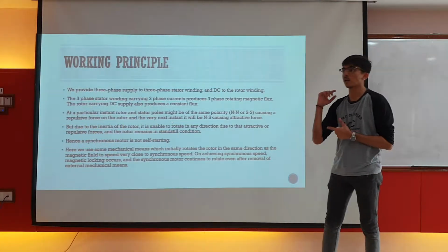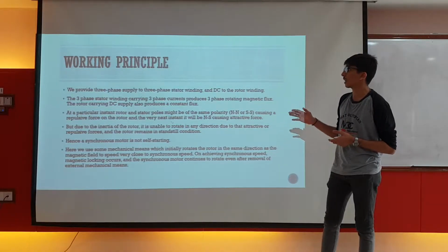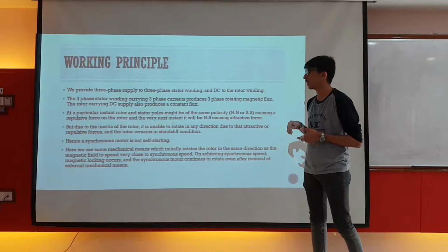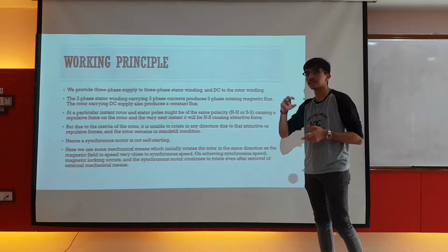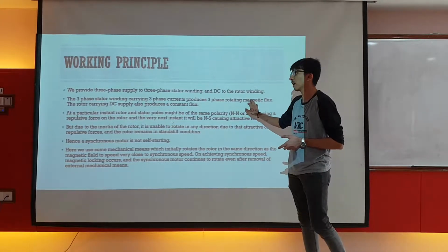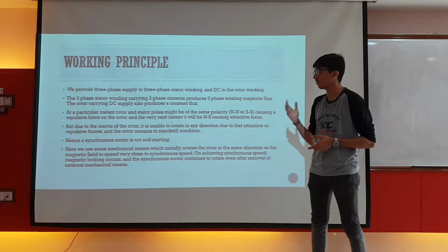So let us look at the working principle of the synchronous motor. We provide three-phase supply to the three-phase stator winding and DC to the rotor winding. The three-phase stator winding carries three-phase current, so the three phases have three different currents and produce magnetic flux. The rotor carrying DC supply also produces a constant flux.